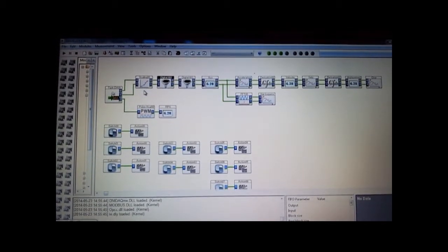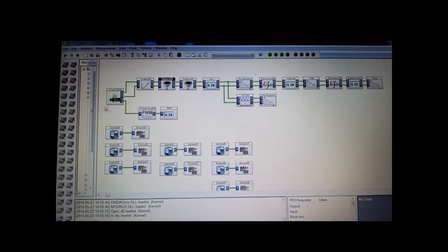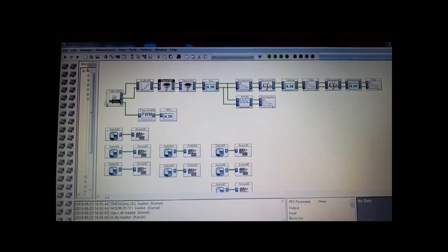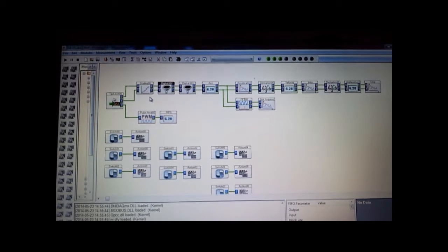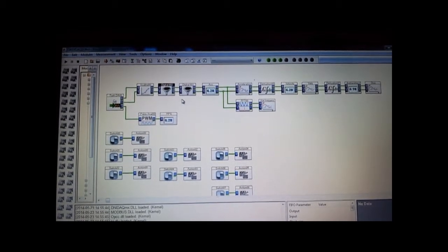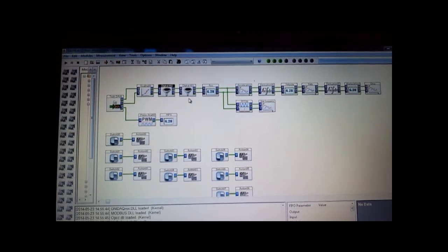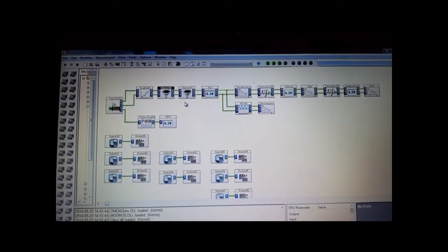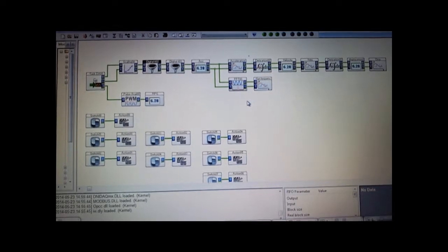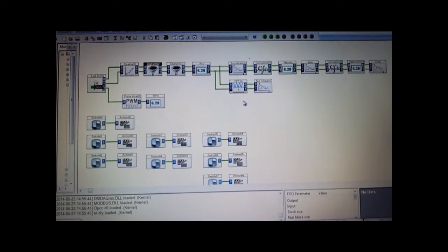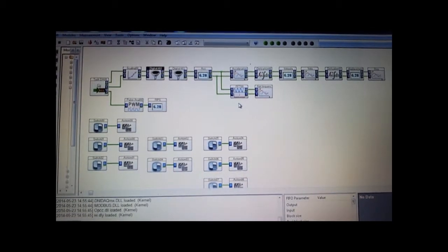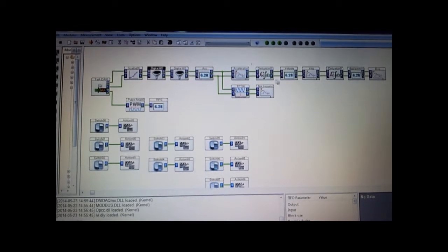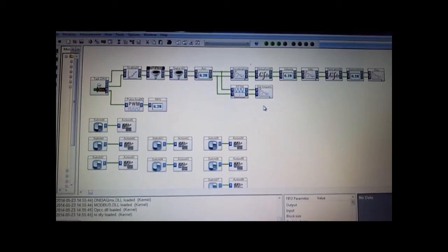Then we move to the DasyLab setup. The data from the NI DAQ is synchronized with the DasyLab setup. Firstly, we do scaling to remove error, and we use 2 filters: the first is a low pass filter and the second is a high pass filter, in order to reduce noise. The objective is to find the natural frequency at different speeds in RPS. We use FFT to obtain the natural frequencies. The speed of the motor rotation is increased to get different values of natural frequencies.